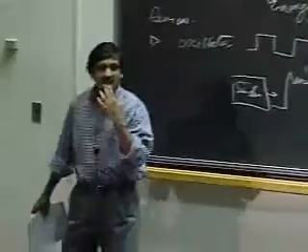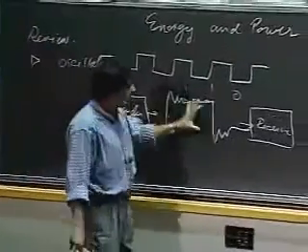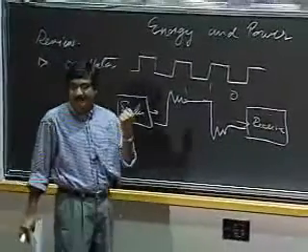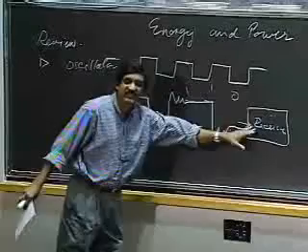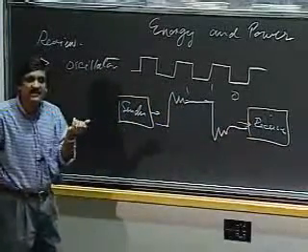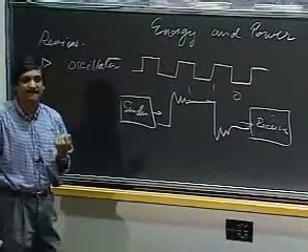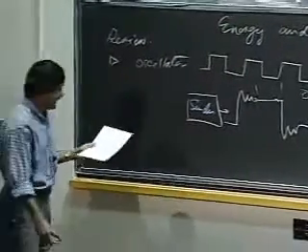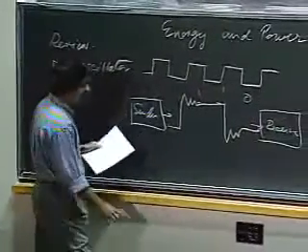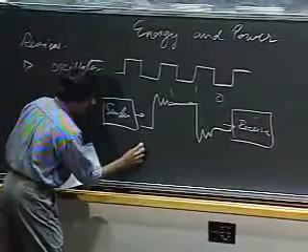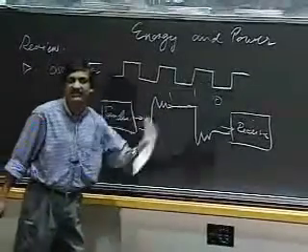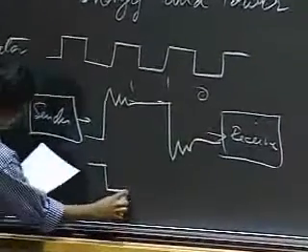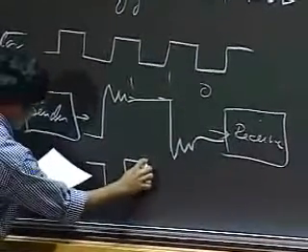It doesn't know. So for senders to be able to communicate with receivers, we need some kind of agreed upon time when receivers sample the signal coming in and decide whether it's a 1 or a 0. They both have to agree on certain time bases when they look at the input. So one way to deal with this is I can have a clock, a square wave signal, which we call a clock in digital systems, and ship it to the other side in the following manner.